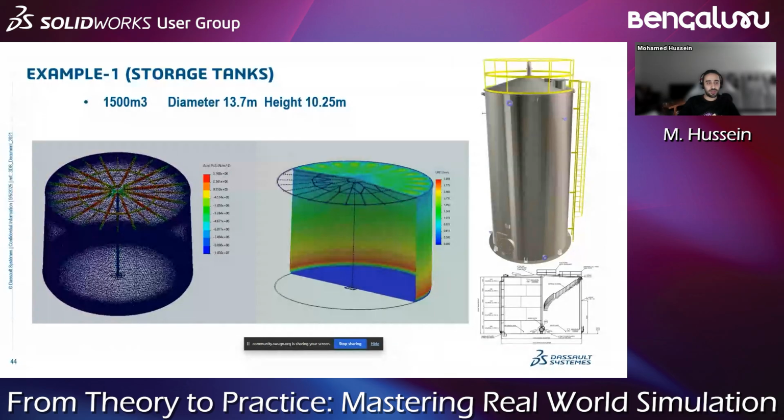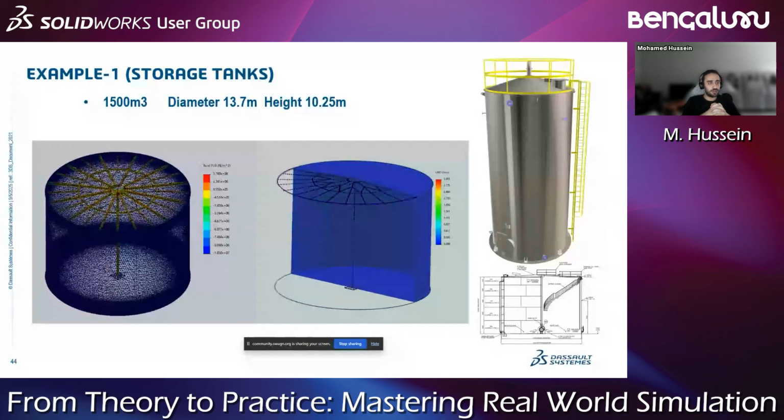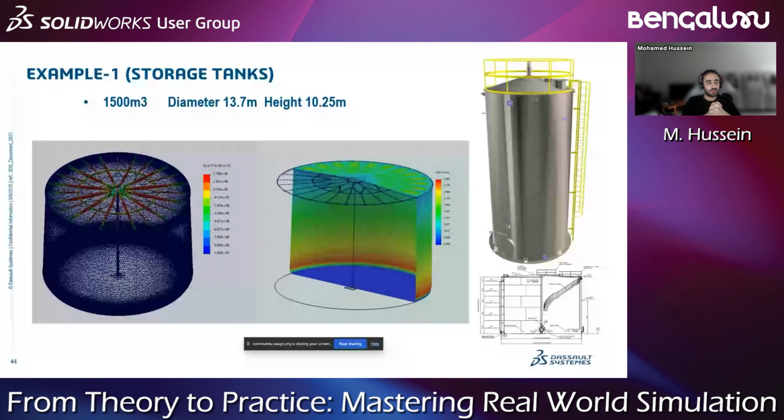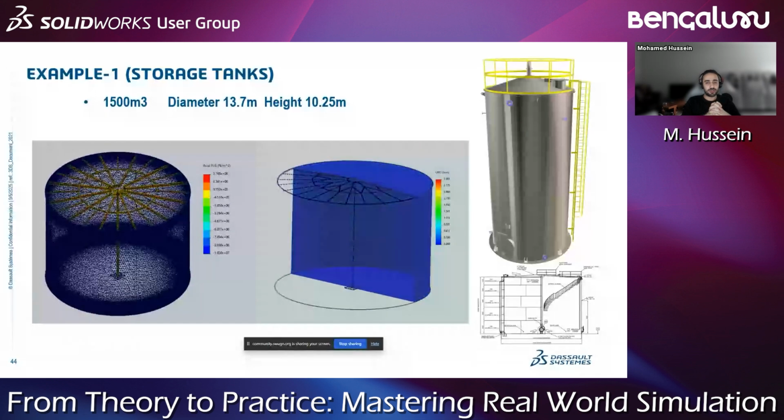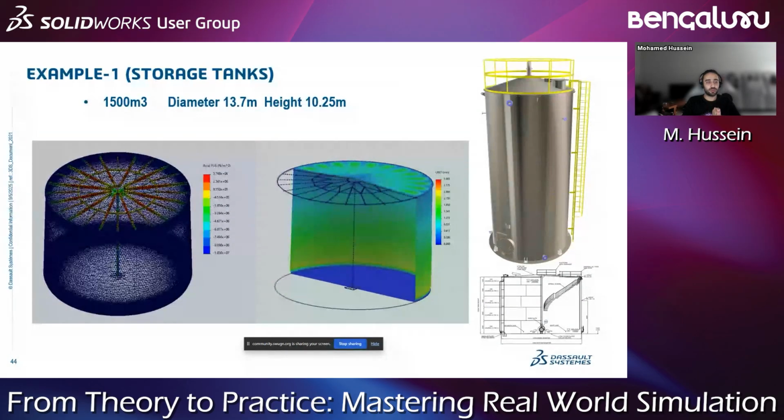Contact is needed whenever you have a multi-body part or an assembly, not only a single part. In our example last week, we had a single part, so we had no need to discuss contacts. But if you are doing any real world example, like what we checked today, you have to use contacts. So what are contacts? Contacts define how different parts will act together.